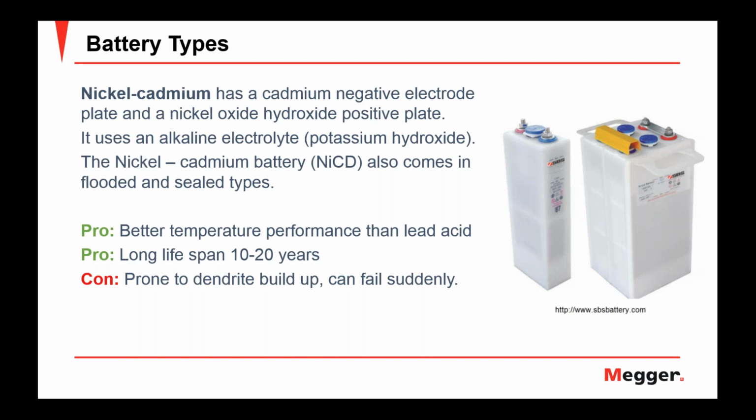In lead-acid batteries, as they discharge, the voltage drops slowly as the impedance rises and the capacity drops. In NiCad batteries, the voltage will remain fairly constant as well as the impedance as the capacity is dropping. It's only toward the end of their capacity will you actually see the voltage drop off and the impedance rise.